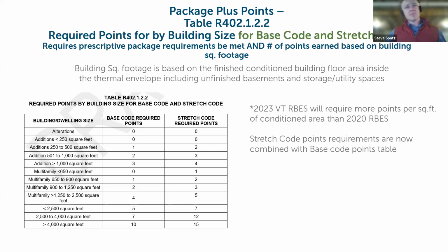Right. Like with HERS, it's based on a numerical score of the overall energy performance of the building. So conceivably in that approach, you could have a building that has higher performing wall assemblies and other components of the building, and yet windows with a U value that are 0.29 average or 0.30. Right. Well, would they look at things like solar heat gain coefficient, that Vermont decided to get rid of or no longer value in the code? Right. So there's just different metrics.